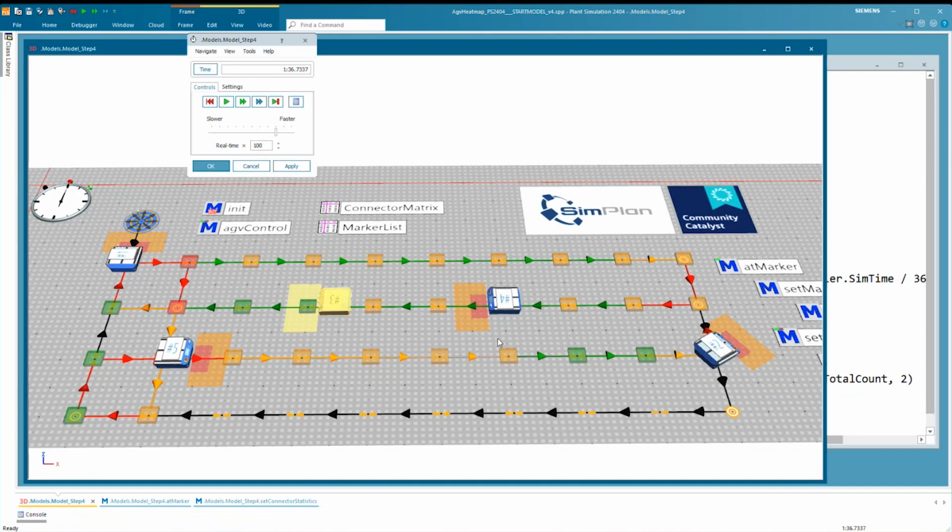For the workers, you don't have acceleration. So if that is relevant, for the AGVs you can consider acceleration processes. If you say for the simulation it's perfectly fine to have a constant speed, then again, you're fine using the workers as AGVs. That should not be a problem.